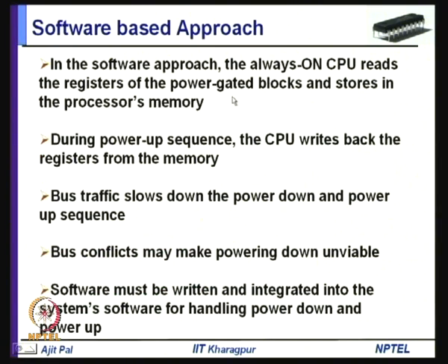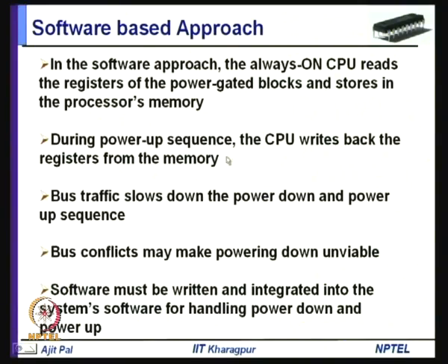In the software based approach, you have an always-on CPU. A program is running which, whenever you have decided to power down a particular block, saves its states by transferring them to some internal registers of the CPU by programming, and during the power up sequence the CPU writes back the registers from the memory. Or you can store them in the memory, either in the register or in the memory. So, bus traffic slows down the power down and power up sequence.